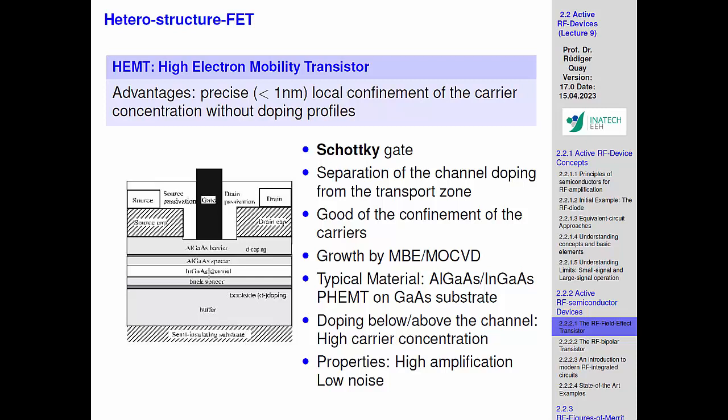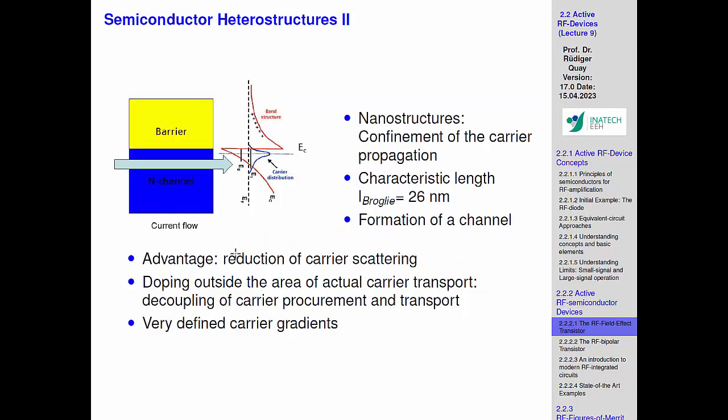And high electron mobility is because the channel itself is undoped, not doped at all. But you have carriers, and where do you get the carriers from? You make a layer sequence, and you put these dopants, now we call that delta doping. You make the channel, you put something on top, and then just at the right distance, you put silicon as much as you can. We put them here in this barrier, but we are not doping the channel, and we just make sure they get close so that they can tunnel. So this is a generic quantum effect which we use there.